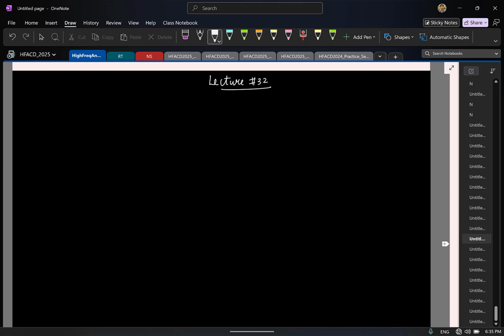Okay, let's continue. So in the last couple of weeks, we essentially were looking at some of the non-idealities that you might encounter while designing analog circuits. The first thing we saw was mismatch, and the effect of mismatch was twofold in our op-amps. First, we noticed that we have what is called a common mode to differential mode conversion. That is, although you have a fully differential circuit, if there is mismatch, if you provide a common mode excitation, you get a differential mode output. The second implication was that you have offset in your amplifiers.